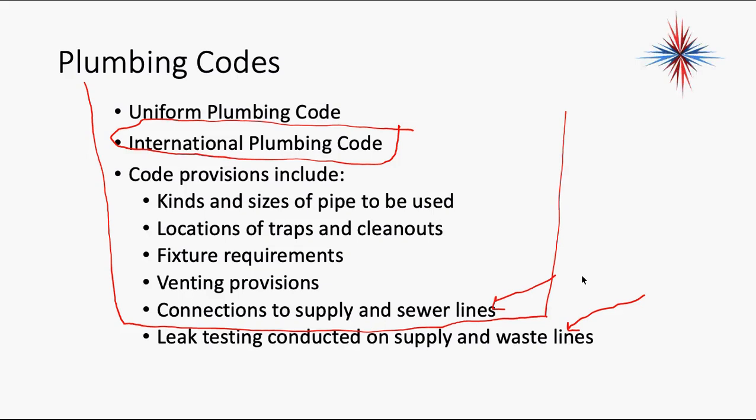For example, in Connecticut, my HVAC license, my S1 license, allows me to do just about anything having to do with gas and any other line after the main. Okay, my HVAC license does not allow me to connect a boiler to the water supply. There has to be a backflow device put in. That has to be put in by a licensed plumber. Once they put in the backflow, I can do anything after the backflow prevention.